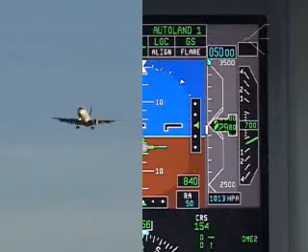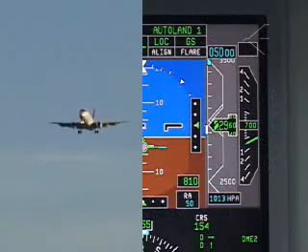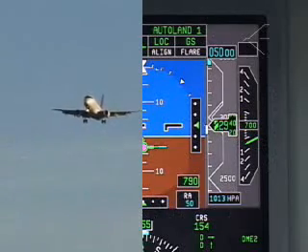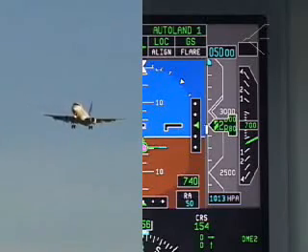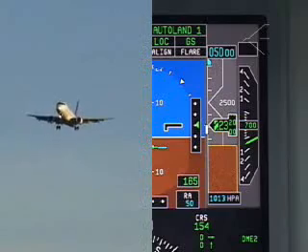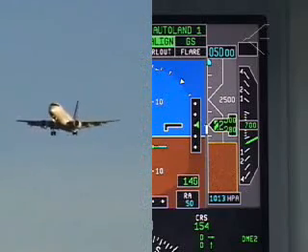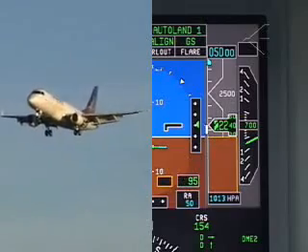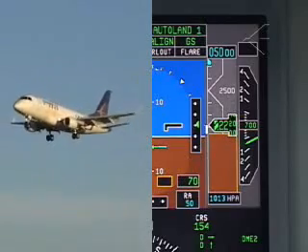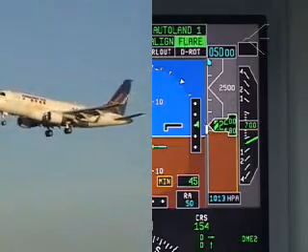During Autoland operations, the automatic pitch trim adds a nose-up trim bias into the horizontal stabilizer trim command at 800 feet radio altitude in order to prevent a nose-down transient in the event of an autopilot disconnect during flare. Also, automatic pitch trim commands are inhibited during flare, derotation, or rollout.